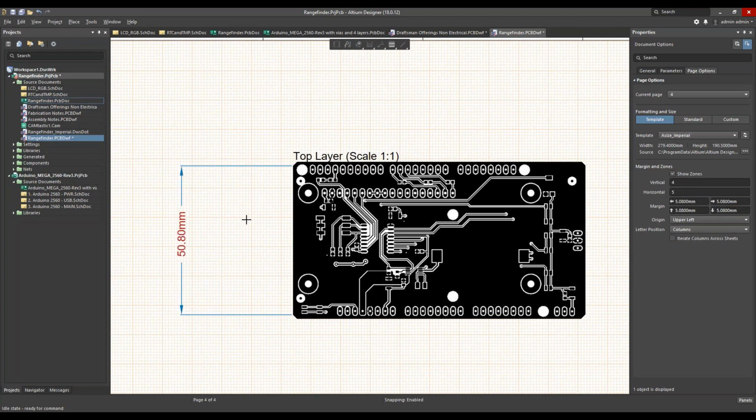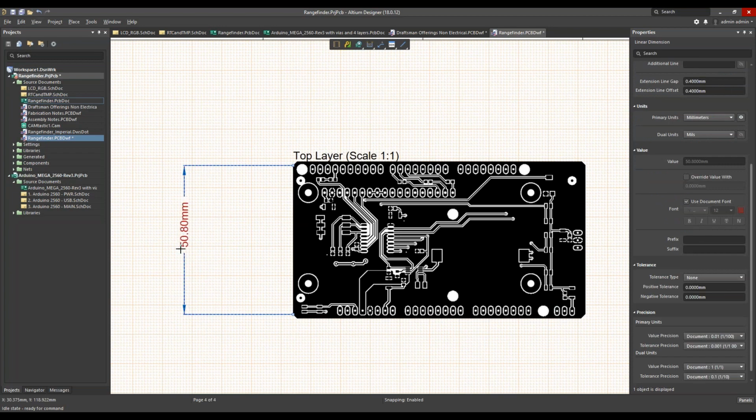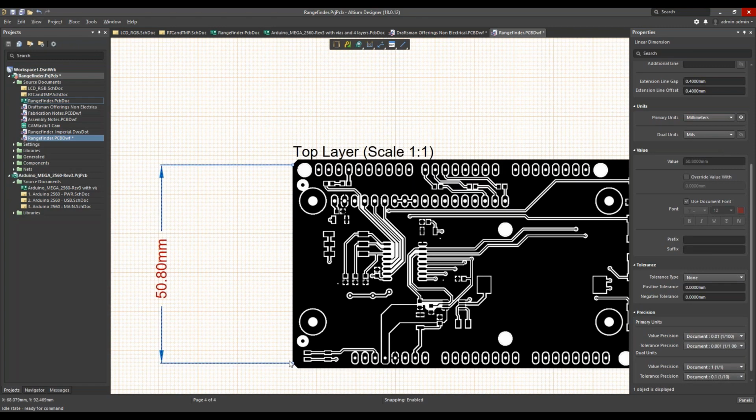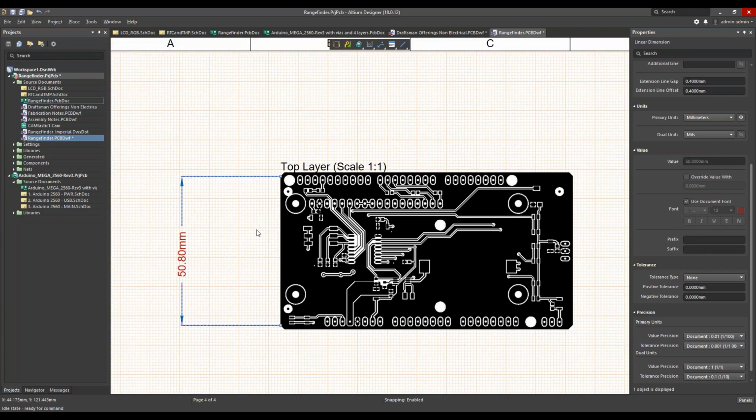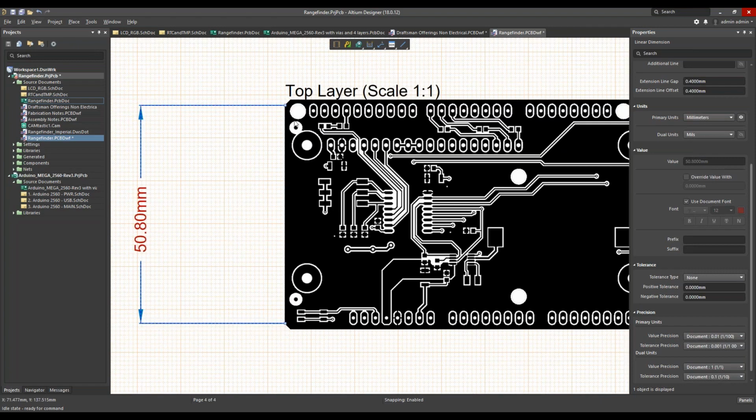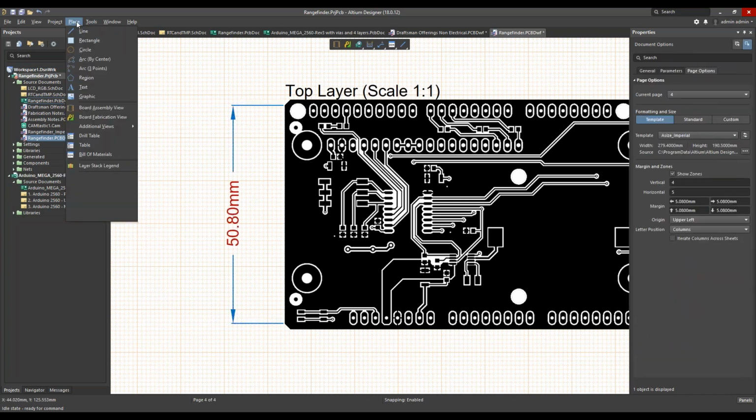It's good to go. The caveat to this one is that once I've got this, I can move this over here. So I can move the information, and I can move this scaling back and forth. What I cannot move are the points in which it's placed down. And by the way, you're going to see this in a number of different features in the Draftsman tool. So if you don't like where you put this, you're like, oh shoot, I really wanted the measurement to be from this point to this point over here, then you would actually have to delete it. But I am going to leave this here, and I'll show you this feature again with the 2 points.